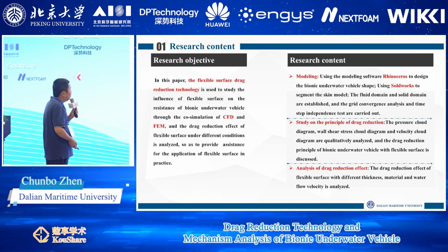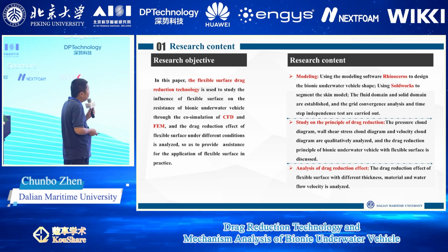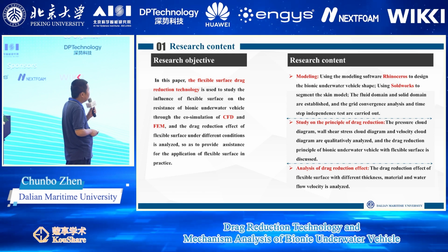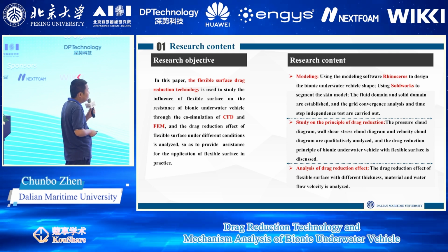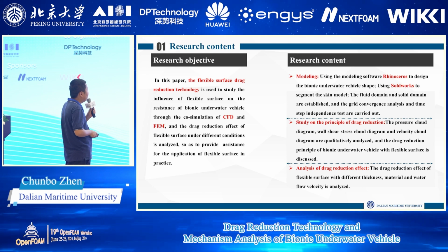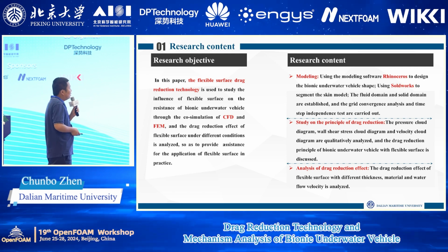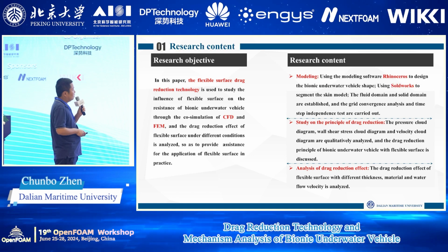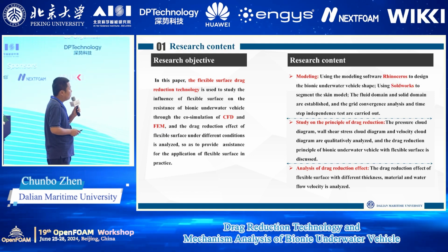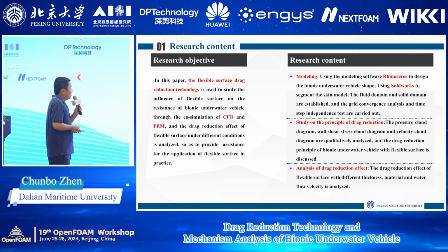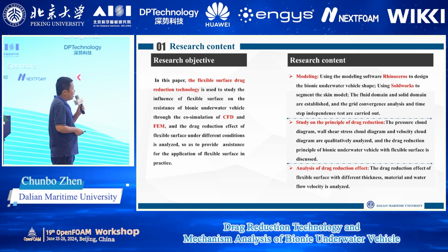The research contents include, first, modeling. Using modeling software to design the bionic underwater vehicle shape, and using SolidWorks to segment the skin model. The fluid domain and the solid domain are established, and the grid convergence analysis and the time-step independence tests are carried out.